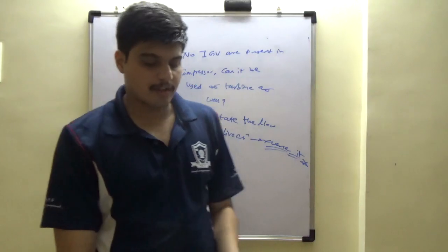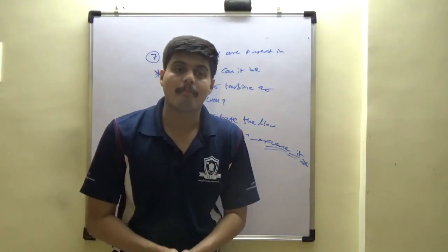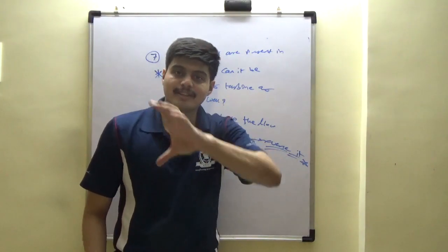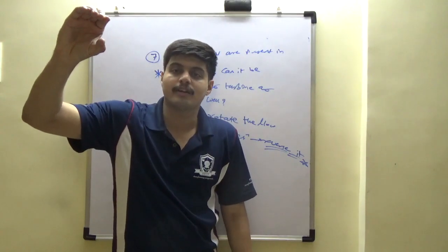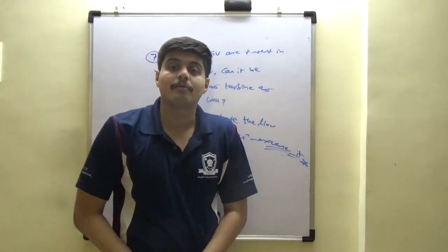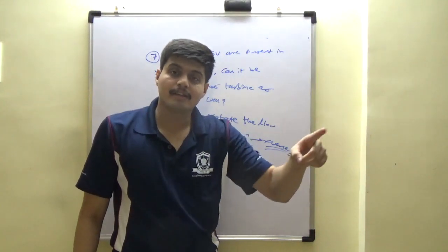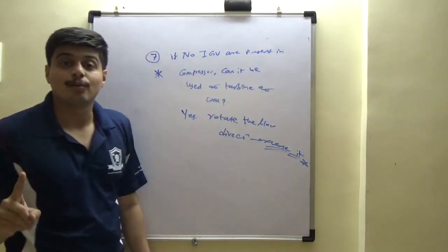Mechanically, there are of course a set of challenges, something called turbine-compressor matching through spools. The hub radius which increases here would not allow your turbines in a small concentrated zone to operate at such a high temperature. So the material science person and the mechanical engineer will not let you do it, but propulsion engineering can let you do it.